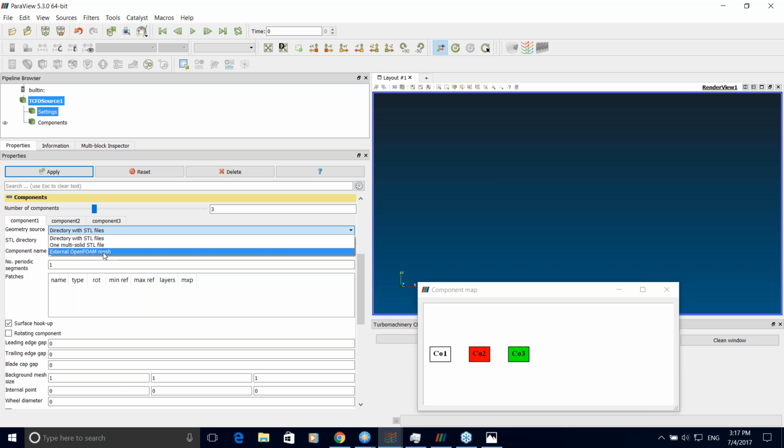So you can use almost any external meshing tool, and the mesh is then converted to OpenFOAM, because OpenFOAM provides a lot of converting utilities for many mesh formats. So we can also use some external OpenFOAM mesh, and the definition will be similar.